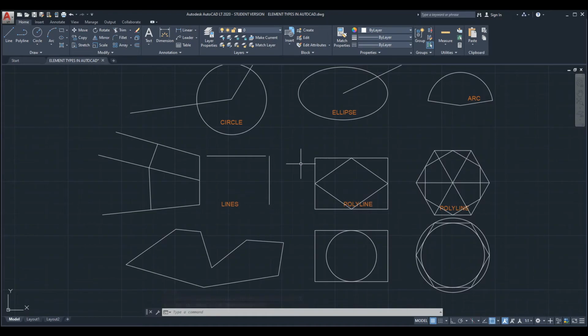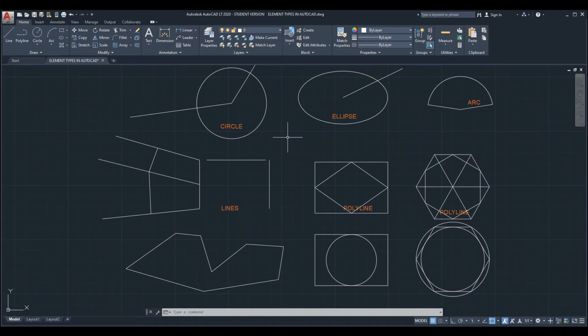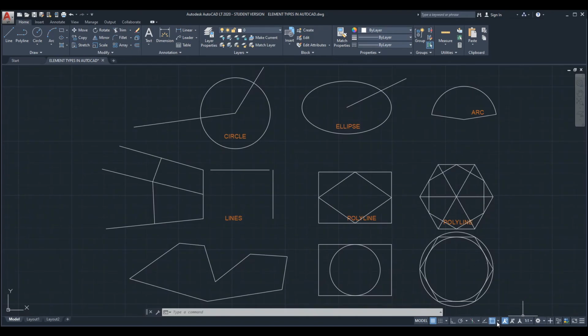All right, and now moving forward with the other snap points we have here, let's talk about the next one. Let's talk about the quadrant. So the circle and the ellipse have quadrant points, which I will show you where they are. They're kind of marked in the quarter of each geometry. So the circle has them here, and they have the diamond shape. A green diamond will show up when you are referencing the quadrants, and the same on the ellipse. If you just come closer to the quarters here, we will get them, and you will see this is the quadrant snap point.